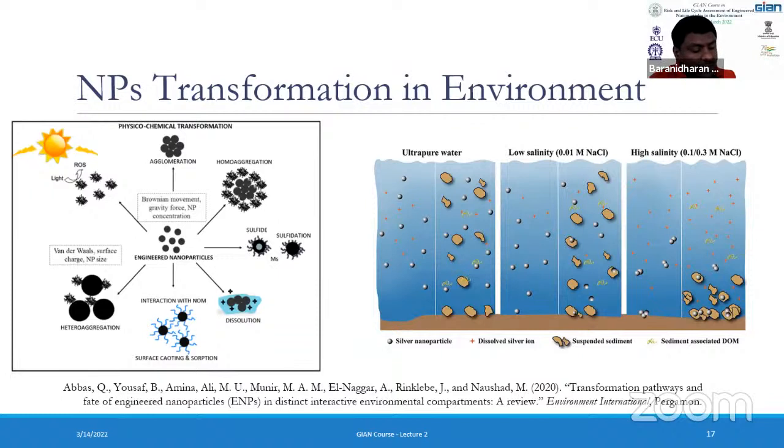So CCC is the most critical concentration of the coagulant that is needed to reduce the electrical double layer. In the natural environment, a colloidal suspension with high values of critical coagulation concentration will obviously be stable enough, whereas stability reduces and the engineered nanoparticle agglomeration rate increases with lower critical coagulation concentration values.